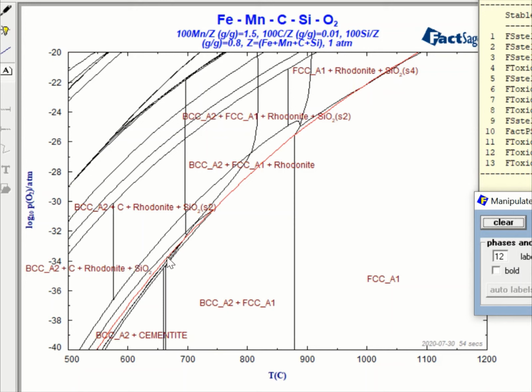It's not. In the phase diagram, as I mentioned before, only for the binary and the ternary system, you can apply the lever rule, binary or ternary lever rule. So you can more or less estimate what will be the amount of each phase forming in each area. But unfortunately, if you go to this kind of multi-component system, even though there's a very, very small amount of a phase forming, you can actually show it as a phase here. So it looks like a lot of solid is forming, a lot of rhodonite, but in reality, it may not be a lot. So you have to be careful.